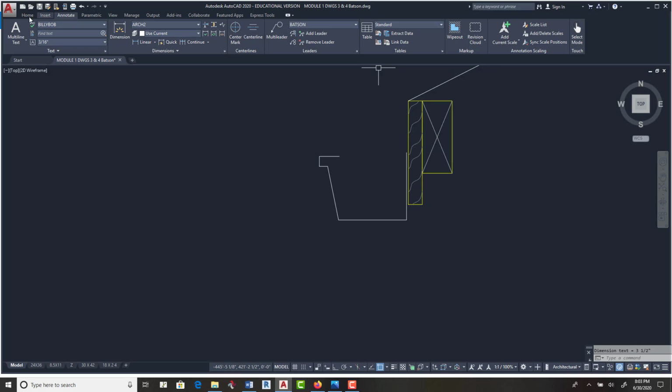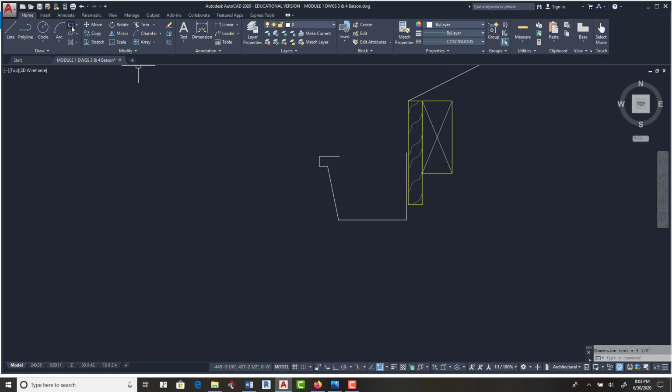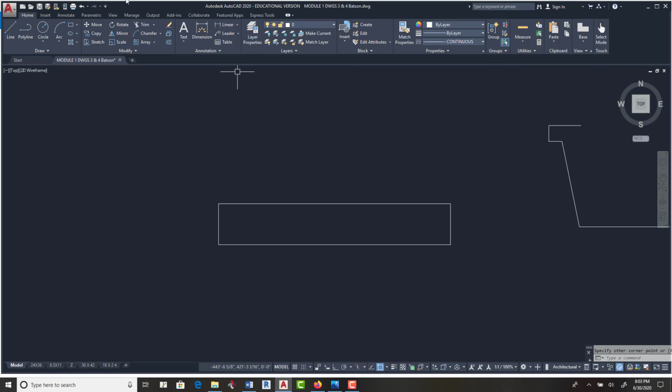And here's the quick way of doing it. If I go to home and I go to rectangle command, you draw the 2 by whatever member, and then you go to SP line, enter. And then you want to click on nearest. So click on your snap, and then just temporarily use nearest. Okay? So therefore you can just eyeball what looks like a grain, right? And then you can copy it. Copy and make it look like a grain. There you go. Oops. I didn't have my ortho on, so I'm going to put my ortho on.